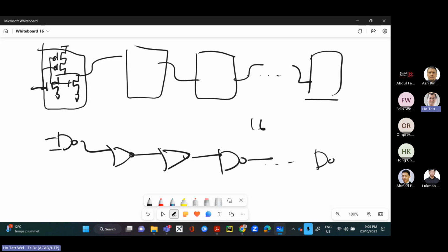Their path has 16 two-input gates. And roughly speaking, they're saying that this has nominal delay. For simplicity, they say the delay is 20 picoseconds for each gate, roughly speaking. That's what they say. Okay. But in reality, I want you to understand this is not 20 picoseconds.